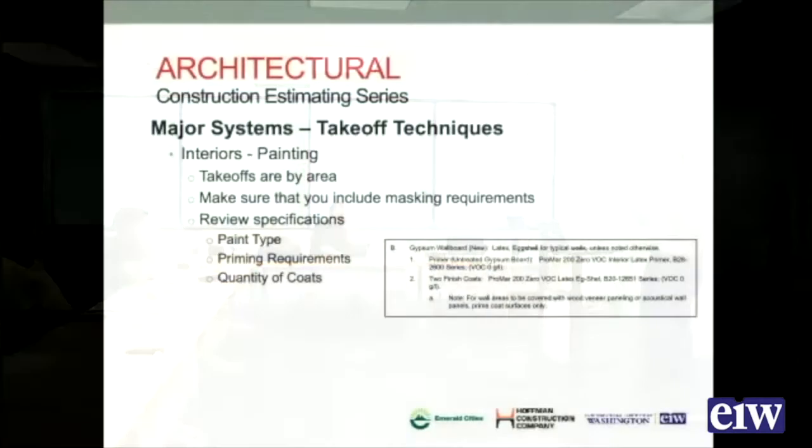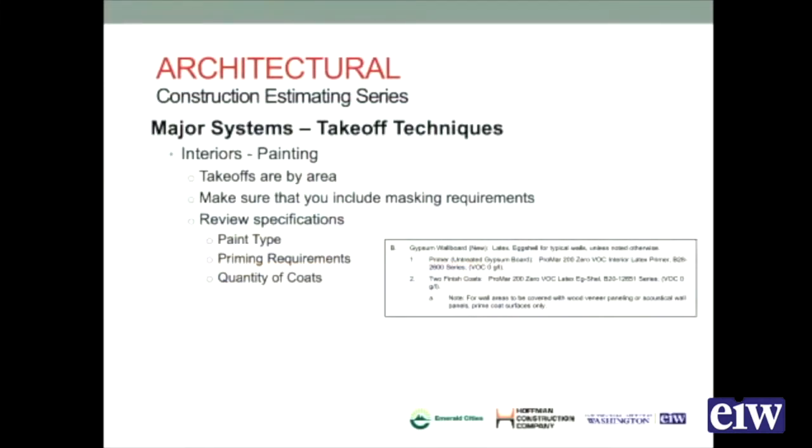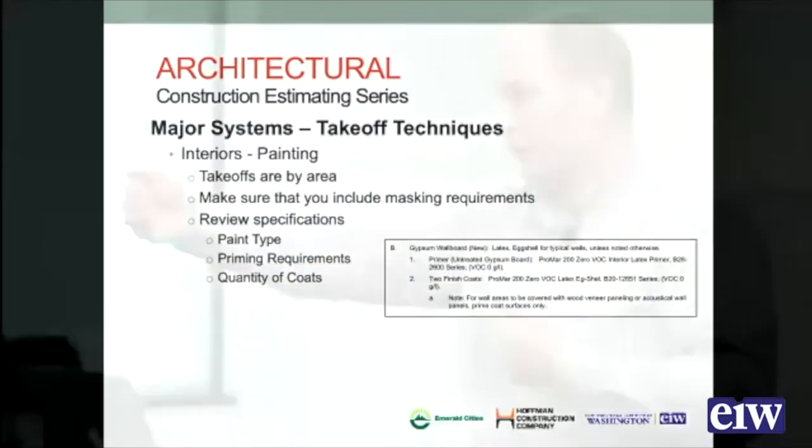Or as you transition, if you've got a wall and then you've got an alcove into that wall, around those corners, that alcove may have a different color paint on the sides that go into it, and then another color of paint on the back wall. So you could have three different types of paint there. You need to make sure you mask it off right, and you understand that time to mask it off and prep the area, because oftentimes paint is going to be going in when you have finished surfaces. So you need to protect those finished surfaces and get the flooring covered up and windows covered up, because you don't want to get overspray on things.